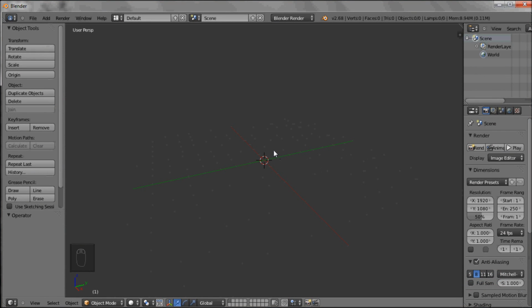So here's another simple project that will introduce you to some more elements of Blender. I'm going to use the grease pencil down here. Select draw, and if I draw, you will see that it draws in the plane that you were looking at. Now we don't want that, so Control Z gets rid of that.